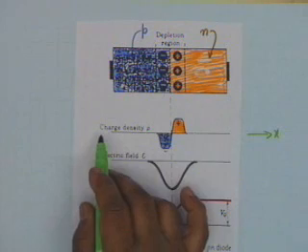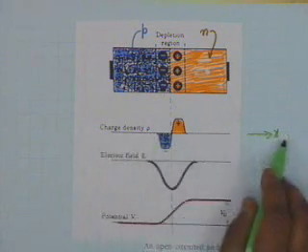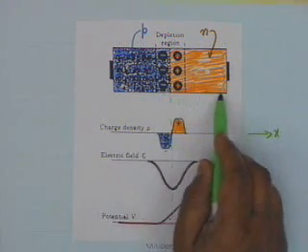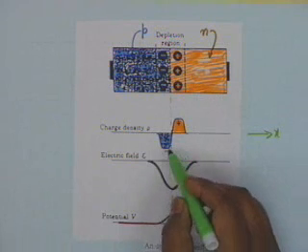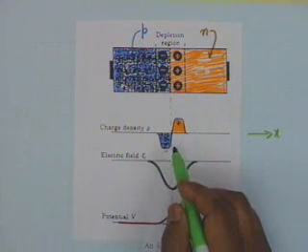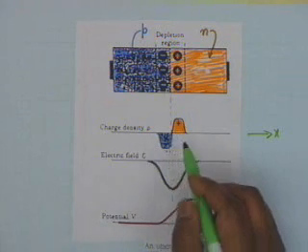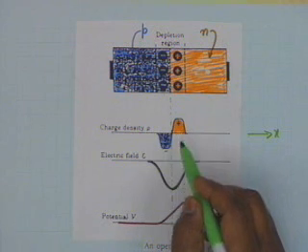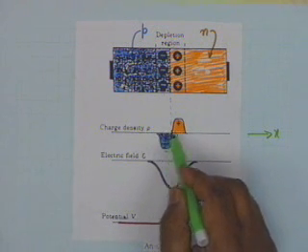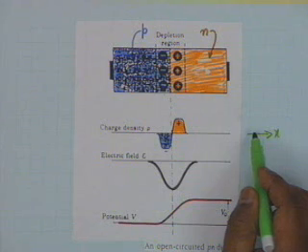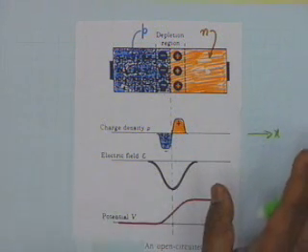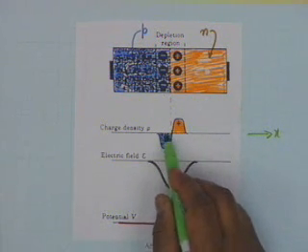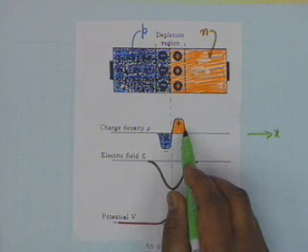if I measure the charge density rho along this, then obviously it is neutral here, so there is no charge. It is neutral here, there is no charge. Suddenly there is an abrupt formation of charge at the depletion region. To the left is negative and to the right is positive. All right. This is how the charge density varies with distance. The charge density otherwise is 0 except for the space charge region. There is negative charge on the left and positive charge on the right.